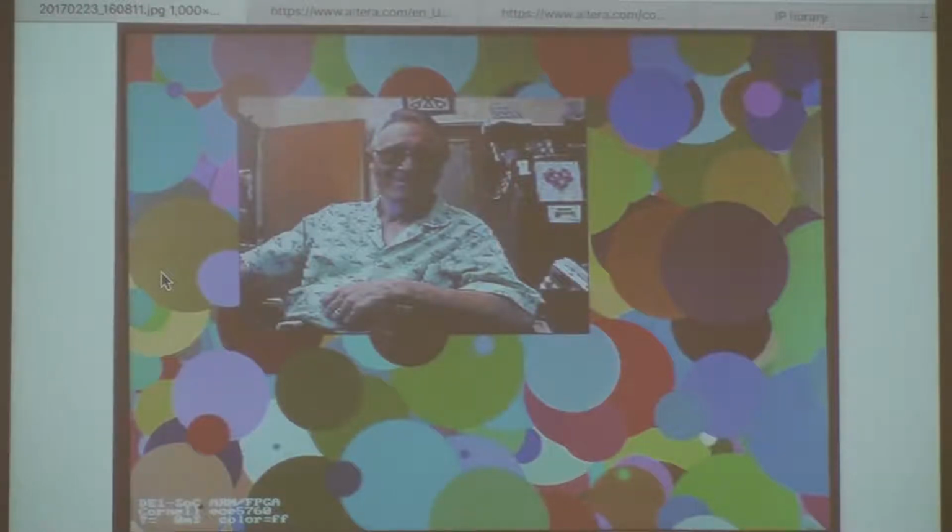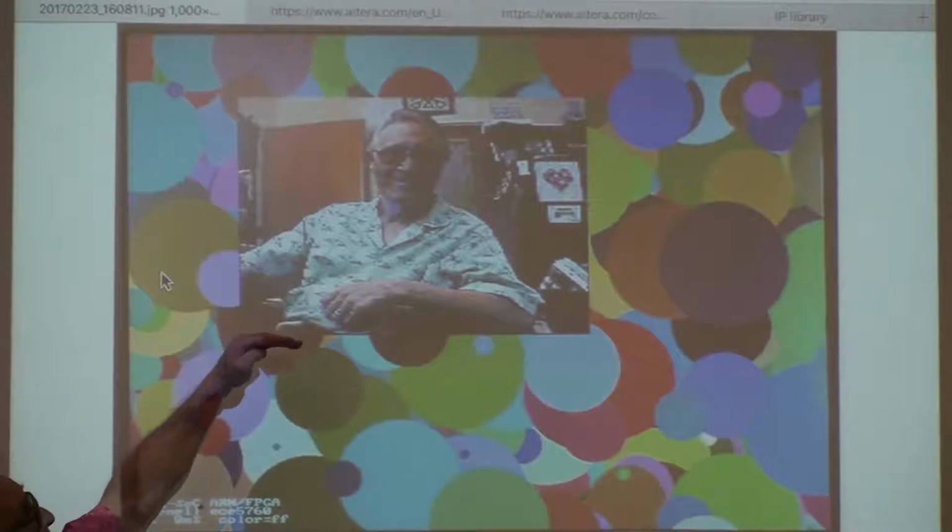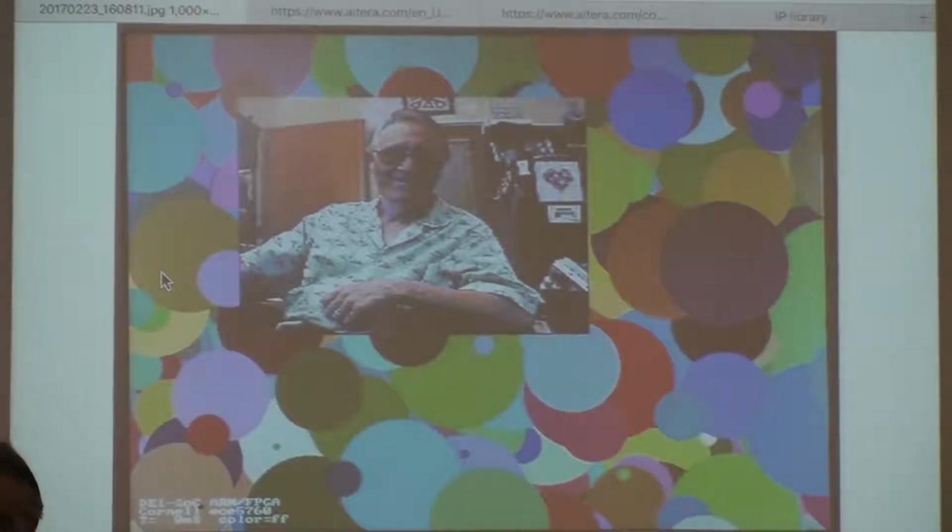However, that's the VGA interface. If you don't go to VGA interface, if you merely record the image into image memory, but don't decode it back to VGA, you can store 16-bit images. Or you can do grayscale. The only artifact that's so far left is that the image moves up and down 1 pixel relative to the VGA sync. It's just enough to say, yeah, I wish it wasn't doing that. So I'm trying to figure that out still.